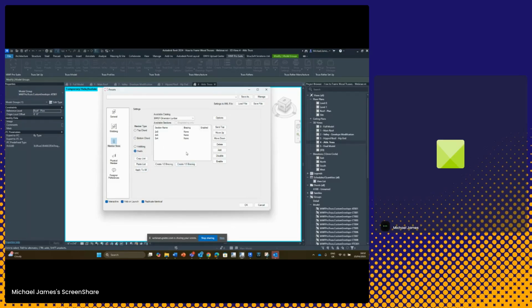Okay, we've got some physical options as well. You've got top track insertion width, and options to add extra insertion thickness if you need it. You've got chord pitch break. So when you've got the top of the truss, you can have the two members overlap, or you can have it open. I'll say lapped. And then you've got chord end cut, which can be cut from the inside or from the outside. You've got the option to define these things here.